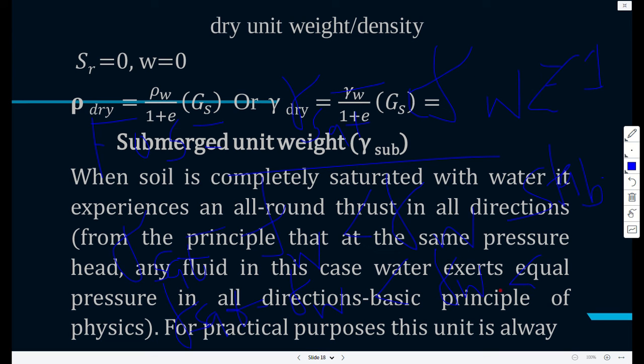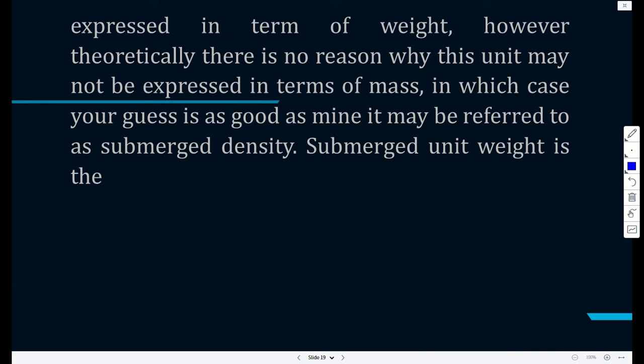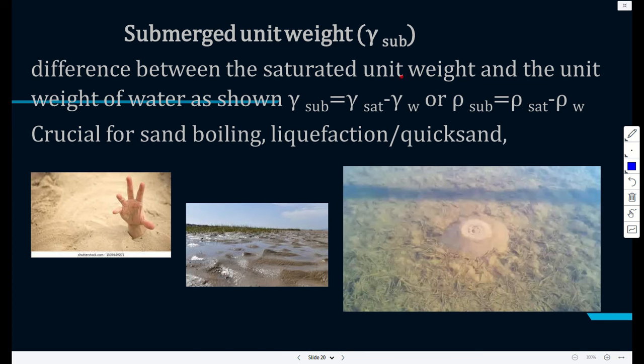So simply put, pore water pressure increases beyond the shear strength of the soil to withstand. So the soil particles kind of become weightless and they're thrown all over. This is what earthquake also does, and this happens in sandy areas immediately after rain because rainwater increases the pore water pressure, as already elucidated. So the submerged unit weight is expressed this way.